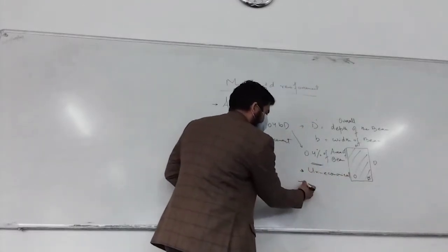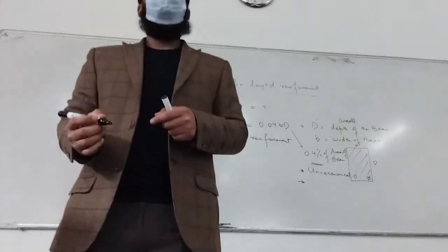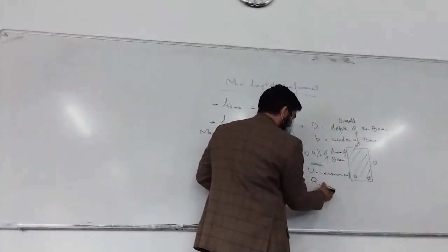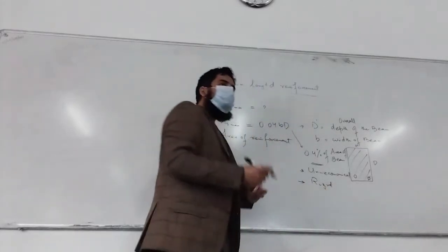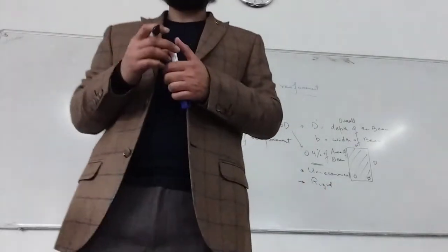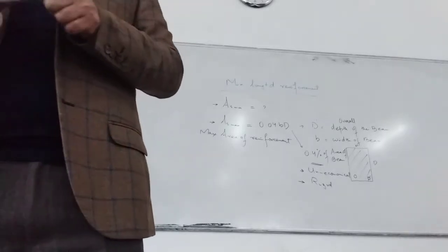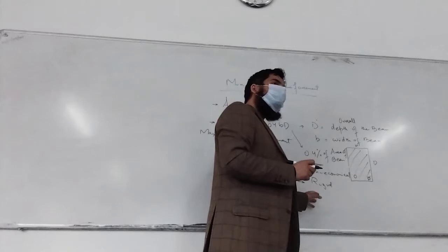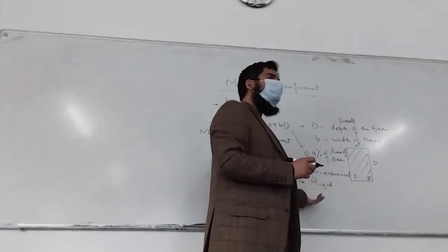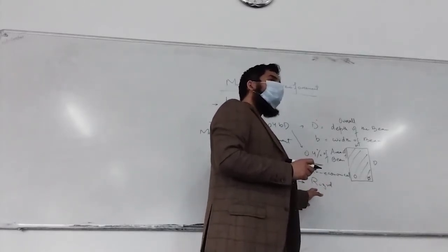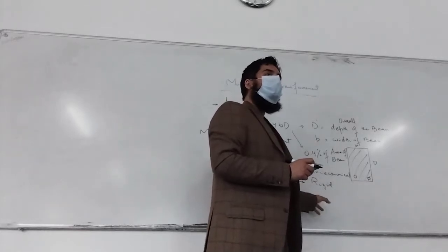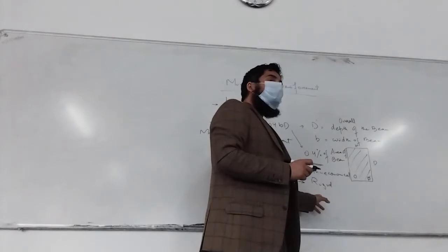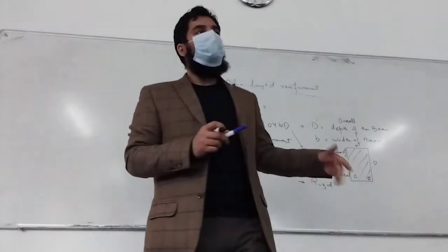Then the second thing that happens is that the section becomes too rigid, because there is a lot of steel and the rigidity is actually increasing throughout the section. So we ensure that it's neither too flexible nor too rigid. Although it might become ductile at the same time, ductility also comes with rigidity in the section.